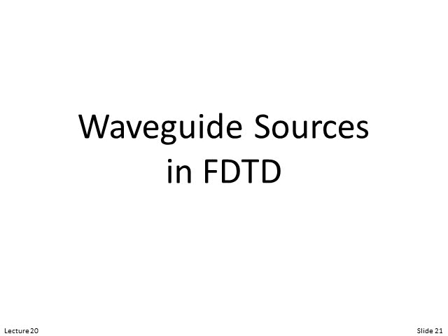Okay, so we discussed some quick theory with slab waveguides. I stepped you through quickly how to analyze a slab waveguide to calculate the modes and gave you all the MATLAB code to do that, and hopefully just enough understanding to sort of believe what's happening in that method. And you can use that code to calculate sources, or calculate the modes. So given those modes, now we need to figure out how to include that in finite difference time domain as a source.